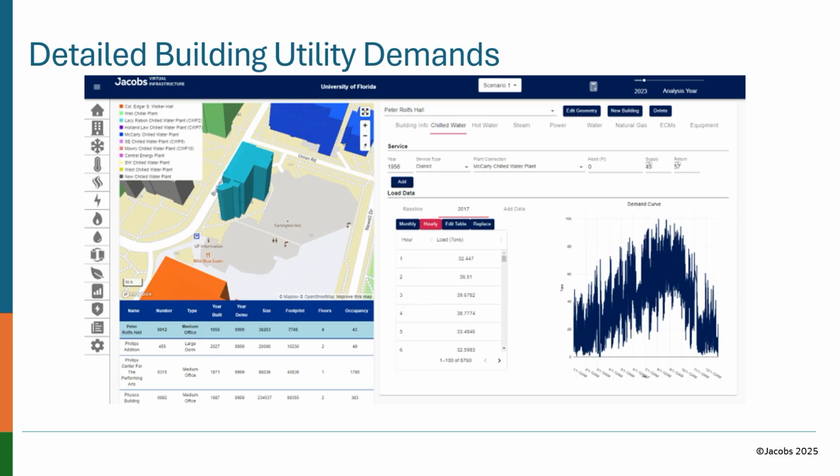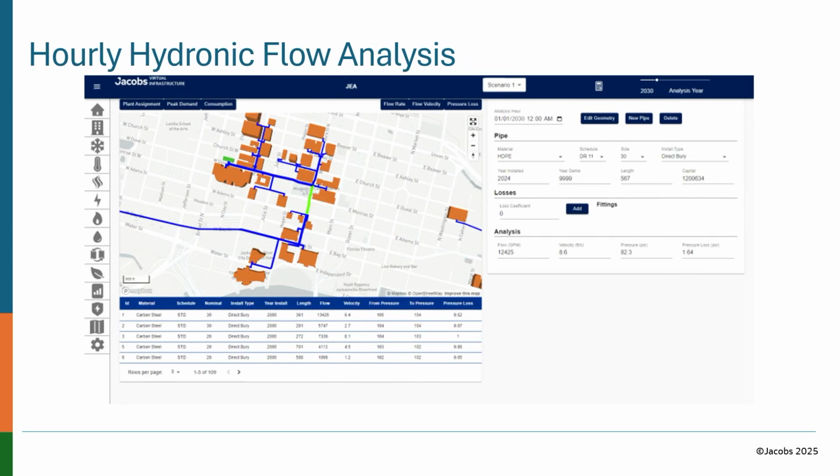But you also are now starting to look at your balanced heating and cooling consumption throughout the year and looking at how far those offsets are time-wise, and that helps us inform just how big that geothermal field is going to be and what that's going to look like. Then a lot of systems that we're looking into hybridizing them. So the excess cooling, the excess heating demand, that's where we're going to start figuring out where are we getting that extra energy from or where are we dumping it to.